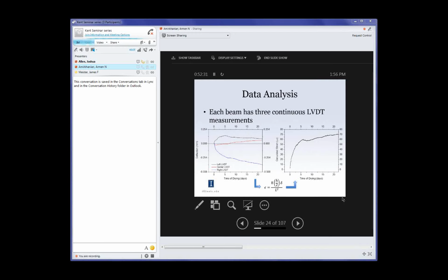So do you normalize one of the LVDTs to the other to determine that? Because if you were in the vertical direction, you wouldn't see it necessarily favoring that. Or if you assume a very rigid base course underneath it, then you would be able to see what happens when it does start to curl upward, creating that U, regardless of the actual contact area in the center of it. Likewise, when it reverts back and you would see the edge of the slabs pushing on it, it would tell you whether or not your slab is lifting off of your base material.